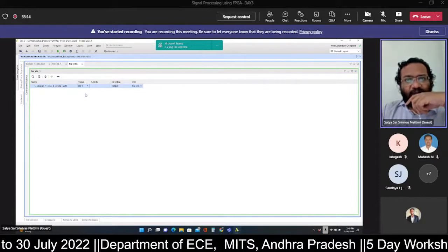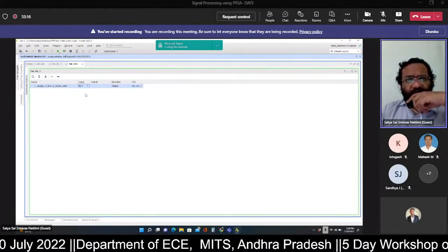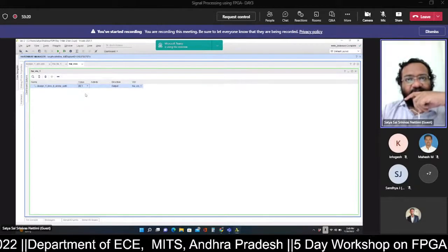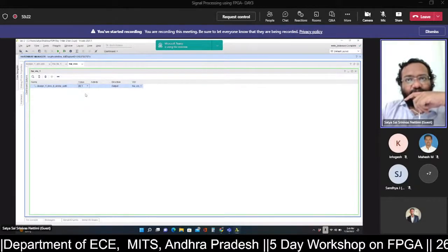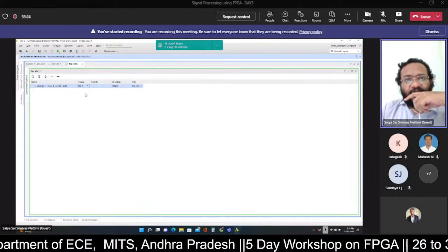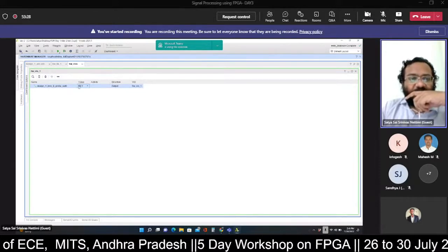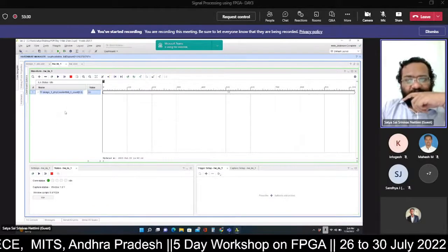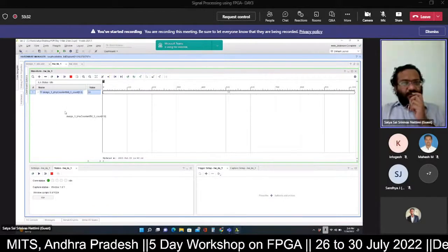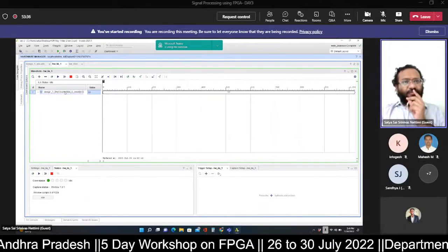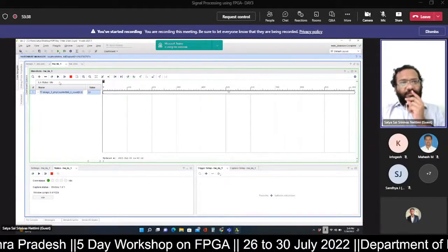As soon as you made the enable value 1, the counter is in free running mode and is continuously generating values varying from 0 to 63. After that, again it becomes 0. Again, the cycle continues forever. So within a fraction of a second, the counter is continuously counting. Now you run the trigger one more time.